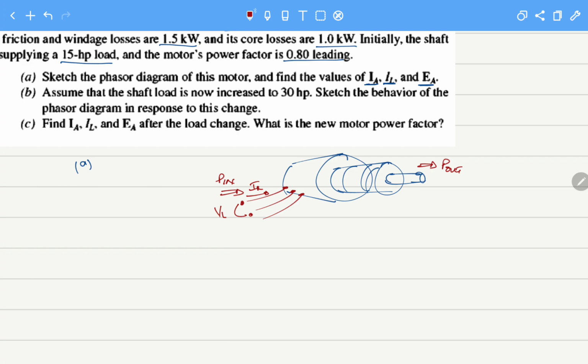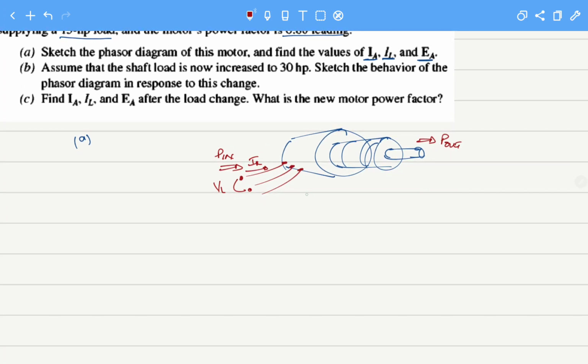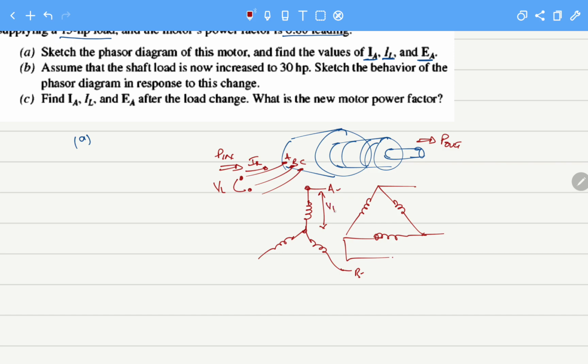Now inside the machine, the winding can be of Y nature, and it can also be of delta nature, and then there becomes a difference in how we interpret these values. For Y connected, if there is a line voltage, then the line voltage is actually between point A and B, so we had to convert this into phasor voltage to make V terminal for per phase equivalent circuit.